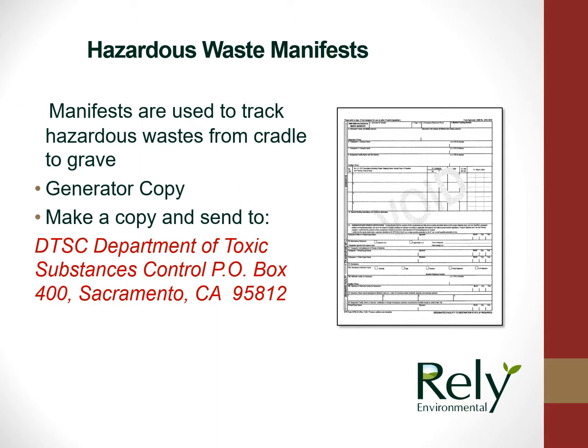In addition, the generator should receive a copy of the hazardous waste manifest from the treatment site or disposal facility within 30 days of having the waste removed from the site. If you do not receive this copy, make sure you notify your Rely Environmental Compliance Associate. We can assist you in obtaining a copy of the manifest or filing a manifest exception report with the Department of Toxic Substances Control.